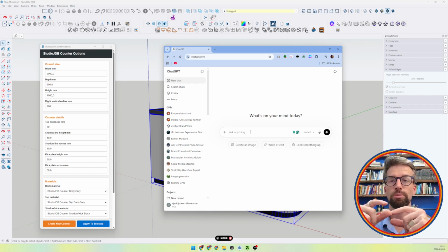Below the countertop sits a shadow line. The shadow line is 10 millimeters deep and 10 millimeters high. The 10 millimeters deep that I describe is the recess of it. All the edges of the counter that are vertical should have a radius of 30 millimeters. Please build this as simple Ruby code so that we can test it in the console.